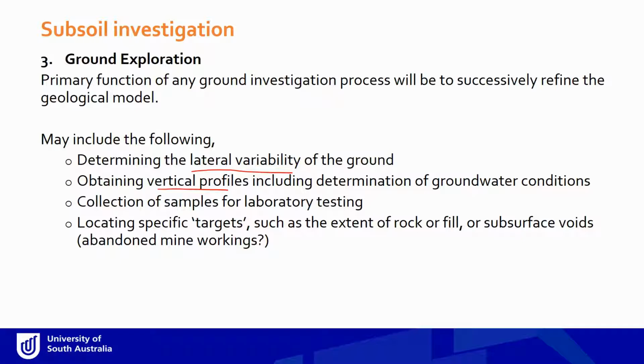What sort of stratification, what type of soil is in a particular layer, how thick that layer is, and at the same time we'll be collecting samples from different layers. In some cases we'll be trying to look at specific targets. Say, if we know there has been a history of mining in a particular area, we might be looking for subsurface voids, or things like that, during this stage.